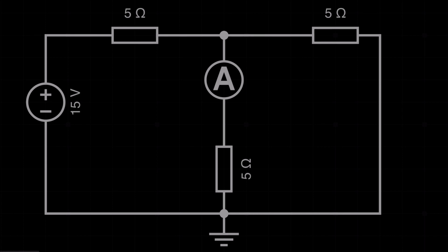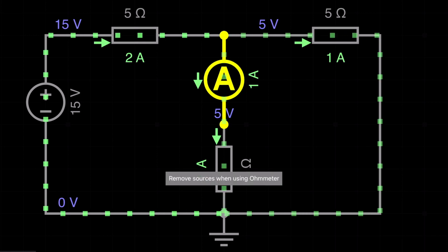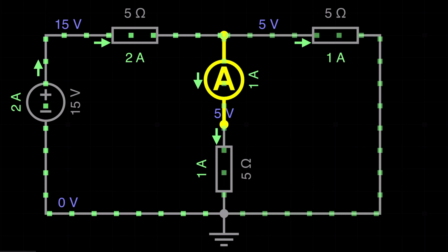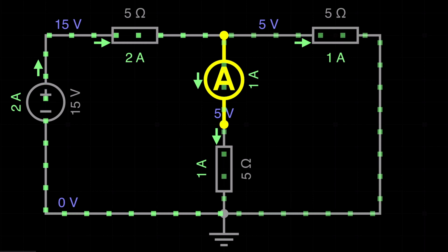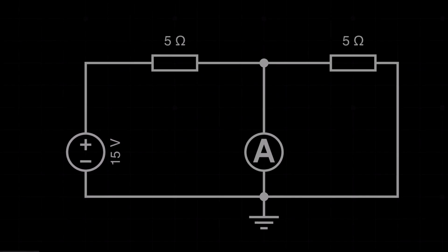So here you can see the circuit is the same just like the Thevenin. Okay, and we already know the load current will be 1 ampere, right? Now what we need to do, we need to calculate the value of ISC and the value of RTH, and we need to check our calculated result is same as the simulation or not. Okay, now let's go to the next circuit, the calculation of IN or ISC.